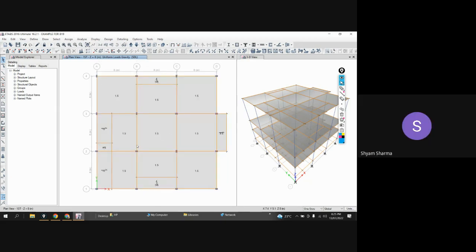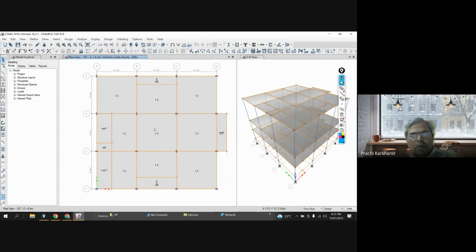No, sir. Okay. Now, this way you can apply the loading on every floor, or you can take the help of that similar story option. If the loading on floors is the same, then you can club it in one group, or you can go to the terrace. Now let's see, we'll go to the terrace and see what the things are.